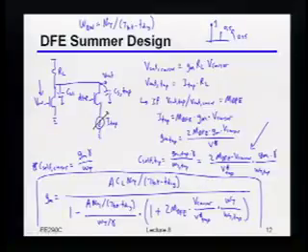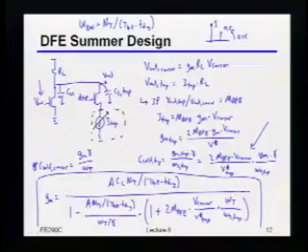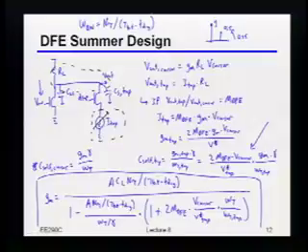In fact, you may even want to pull this thing so that physically in the layout, it's sitting somewhere halfway across the chip, just so it's not screwing up your nice, clean, high-speed signal path, where you want as small a parasitic cap as you can get. So you're absolutely right. If you really hard switched it, you might be asking for trouble. So indeed, you typically leave that in saturation to act as a shield from all of the junk underneath. So you sort of keep it higher impedance than the load. Exactly.